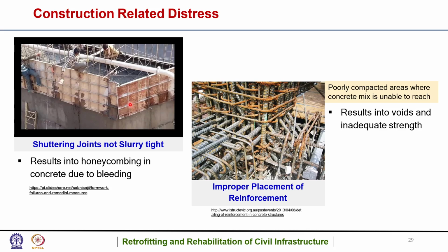Okay, in concrete, bleeding is basically water coming out. So that will again result in shrinkage also. One more factor for construction-related distress can be improper placement of reinforcement.